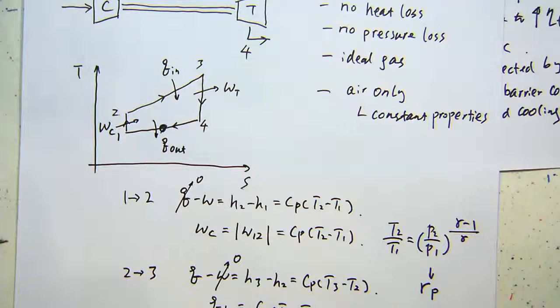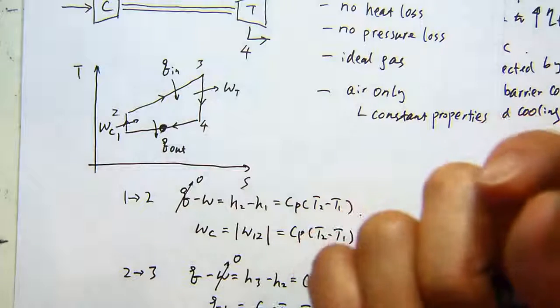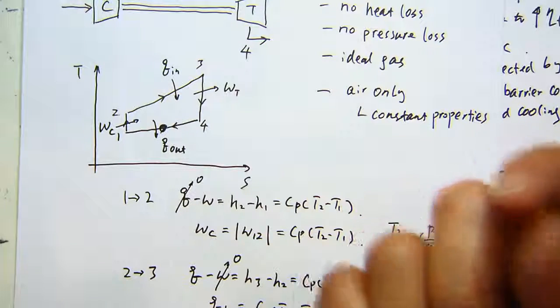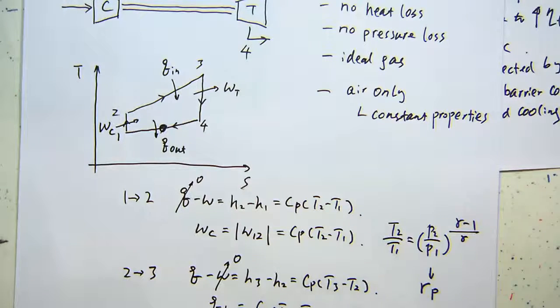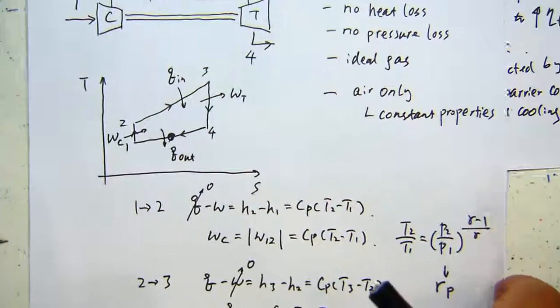But as we will see later in chapter 4, when we're talking about the steam cycle, you can combine a gas turbine cycle with a steam cycle, then create a very efficient process, somewhere around 60% in terms of the output work versus the input energy. All right.